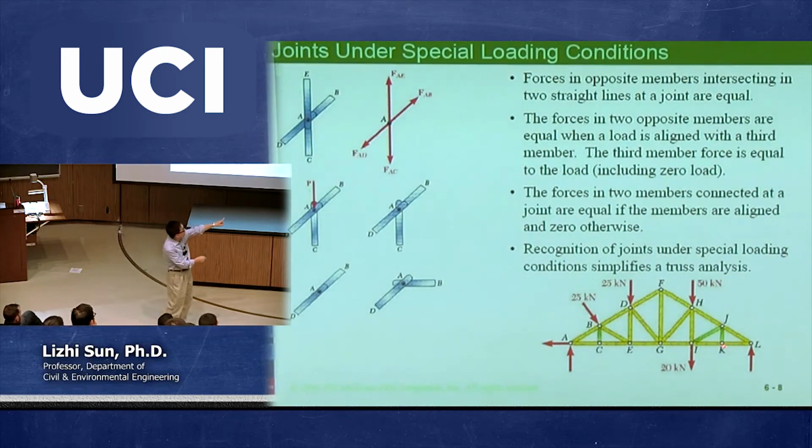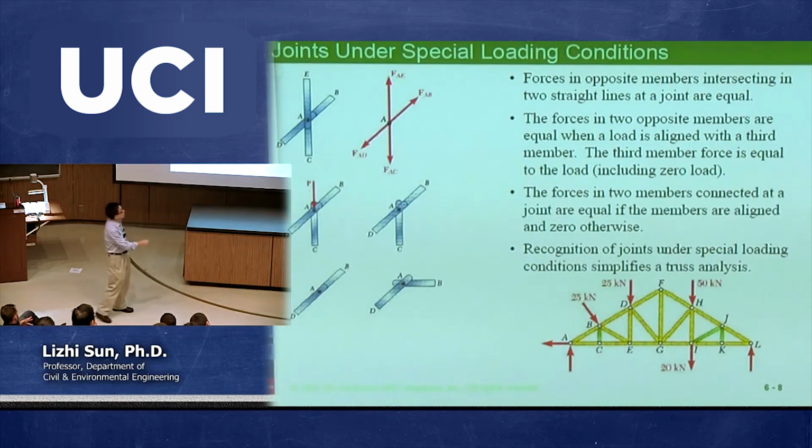Okay, so now I'm moving to this one. If I move to joint K, this should be the same as this one, having 3 members connected, 2 of them in one direction. Then the third one is having 0 force. And you will say, well, wait, that's different because this J is having 4 forces. I'm not talking about point J yet. I'm talking about point K, or joint K. From this joint, I have the conclusion. You can challenge my conclusion, but I already showed you using Newton's law to demonstrate that this equals 0. I'm not making any guesses, right? I just basically showed you using 2 fundamental Newton equations to get a conclusion.